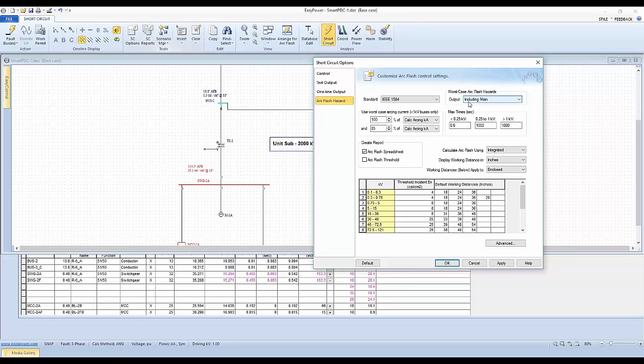Now, it also brings up the discussion like, well, if we have the ability to put up a temporary boundary, if for some reason we need to do work on this bus, and this high number is by virtue of the fact that we excluded the main breaker, does it make sense to consider what constructing a temporary boundary would do?